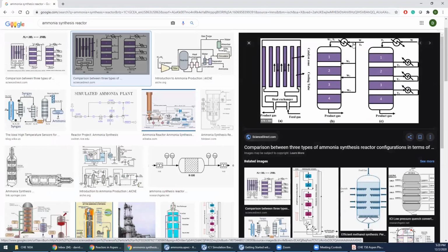If these are highly exothermic reactions inside these beds, you have cold shots. So your cold feed relative to the reactor, you can have one coming down, go through bed one, you have your second feed going through bed two and all that, and that helps you manage all of the heat that's being generated in the reactor.